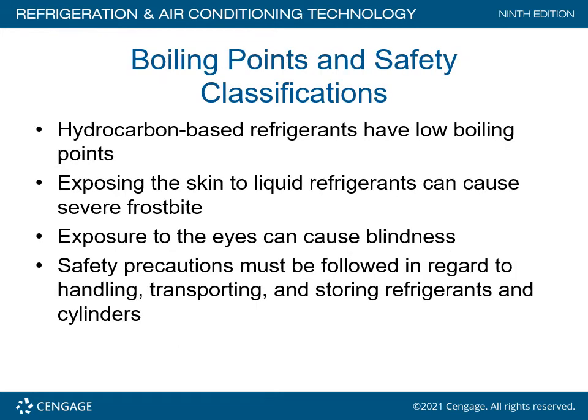Boiling points and safety classifications. Hydrocarbon-based refrigerants have a low boiling point. Exposing the skin to liquid refrigerants can cause severe frostbite. Exposure to eyes can cause blindness. Safety precautions must be followed in regard to handling, transporting, and storing refrigerants and/or cylinders.